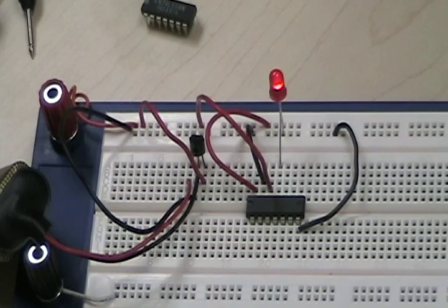So it doesn't matter what I do with the second one. Digital gates are very, very simple. You've got to look at the data sheets, find the pinouts, and make sure that you ground everything properly and you're limiting the power supply to 5 volts. And yeah, just be really careful. I'll show you a couple more. I'll show you the NOT gate and the NAND gate, and then that's going to be all for this lesson. Hold on for 1 second.